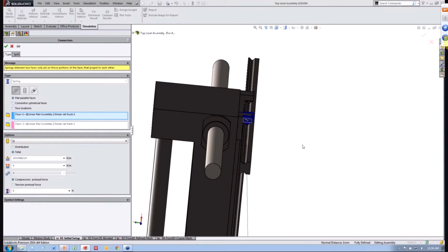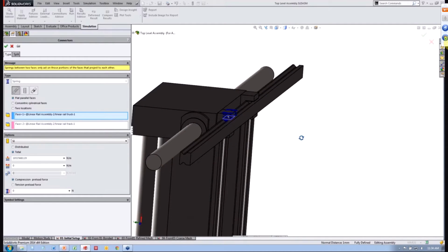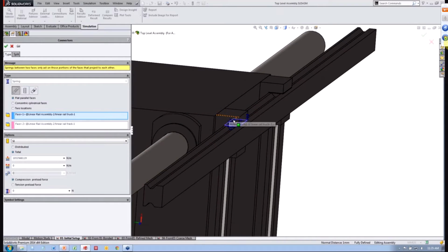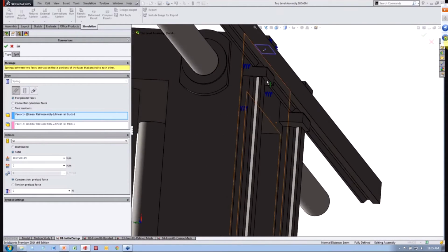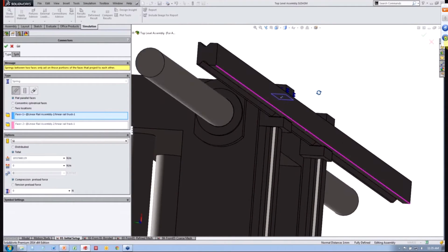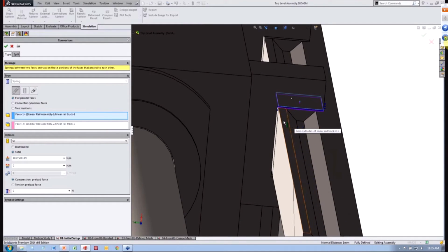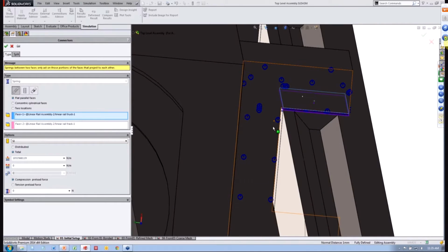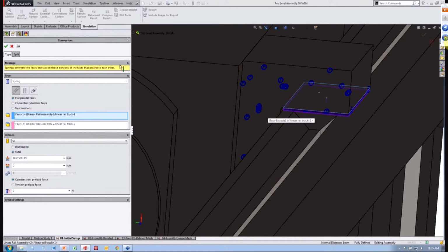Depending on the orientation of the truck, we chose to define just the normal stiffness, but the value that we used was either the lateral loading stiffness for these two faces, this one as well as the opposing face here that connected the linear rail to the trucks, or the average tensile and compressive stiffness that we got on the faces that connected the top of the rail to the underside face of the truck.